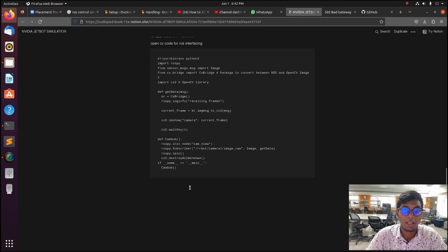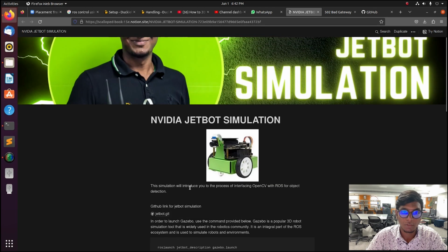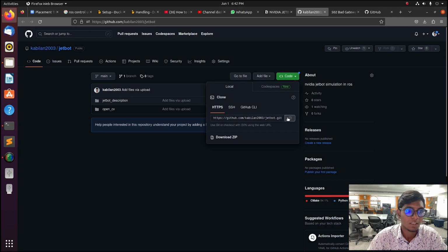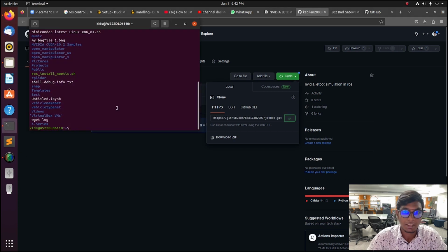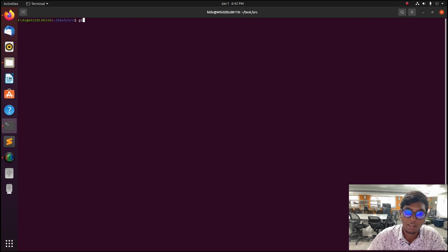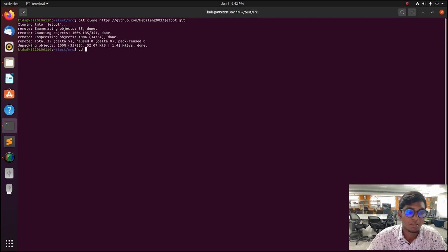Follow that. The whole design of the robot was done by me in Fusion 360 and converted into the URDF format, and I added plugins and cloned it into a GitHub repository. I give the GitHub link also in my description. Copy the repository link, type git clone and paste the link of that repository. After that, enter it and run catkin_make.